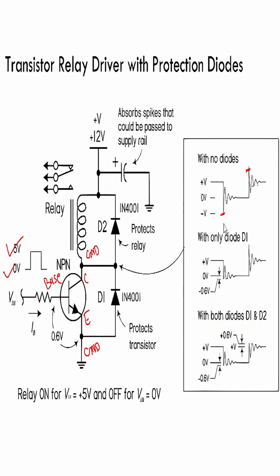How is this spike generated? What happens when this circuit is suddenly off? The circuit was previously working, but due to induction, when it is suddenly switched off, the back EMF will be created here. Why is the back EMF created? Back EMF tells the circuit to keep flowing the current as it was previously.